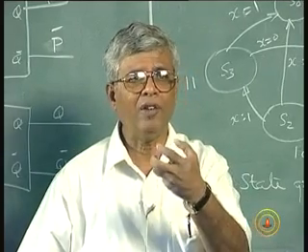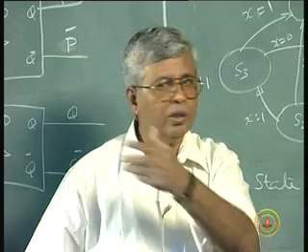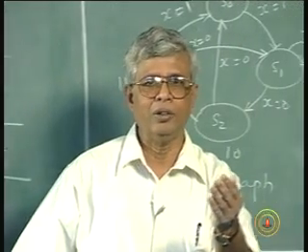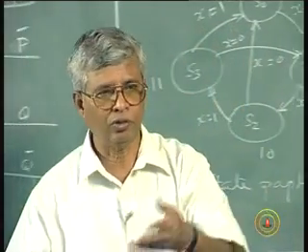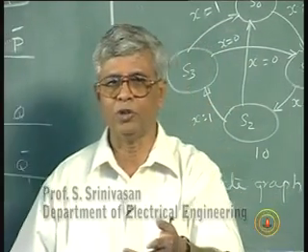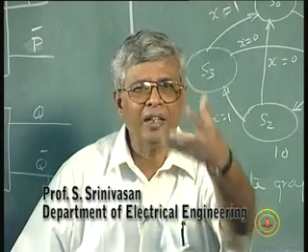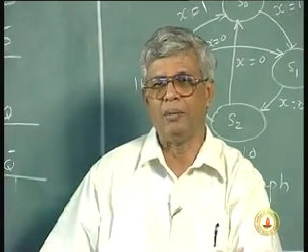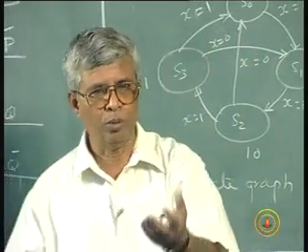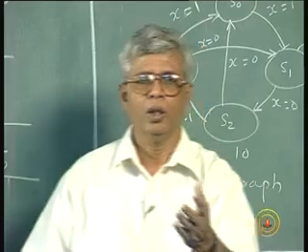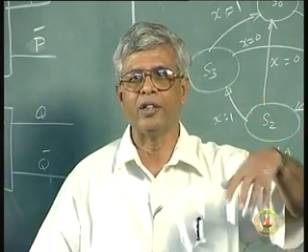So in other words, we now have a tool. We have studied combinational logic, different implementations. We have studied the basic sequential building blocks, flip flops, counters, shift registers and so forth. Now we know a mechanism of representing a given system or a subsystem by means of a state graph. Of course, we are assuming it is a sequential circuit. And once you have a state graph, you know how to proceed and implement it in hardware using gates and flip flops.